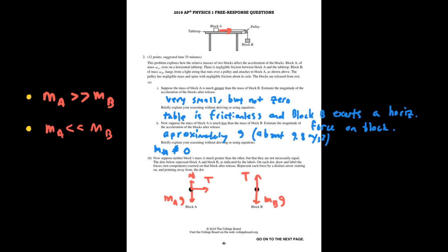So I think those are a pretty good couple of free body diagrams for those blocks. Perhaps I should have shown more clearly that the weight of block B pointing downward is greater than the tension pointing upwards, because the system is accelerating to the right and downwards. Other than that, I think we've got all the forces on there.